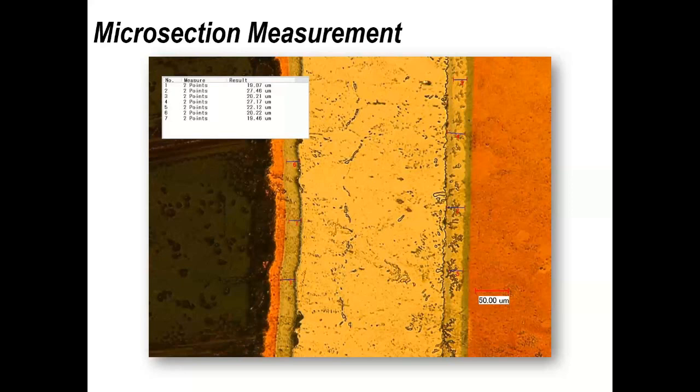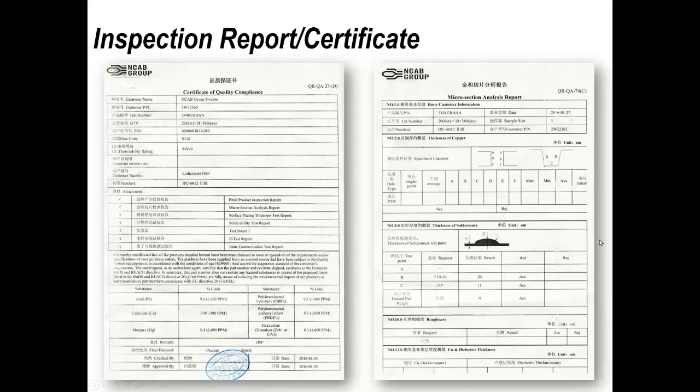If it's a manual system, that matters; if it's automated, then it shouldn't be an issue. But always check that the calibration of the system that you're using is right against something. Normally a glass standard, a glass master, is the normal way of checking measurements out and comparing them.